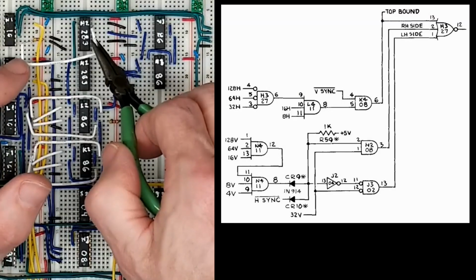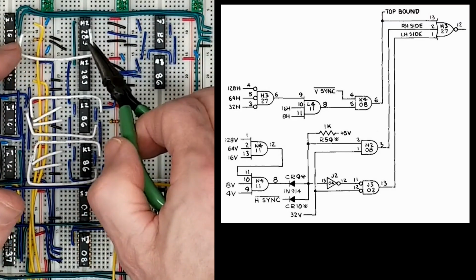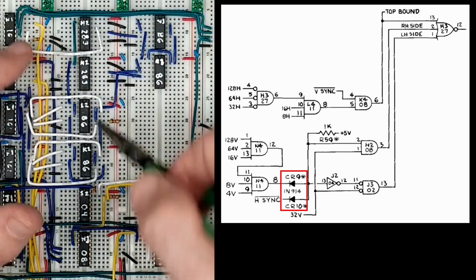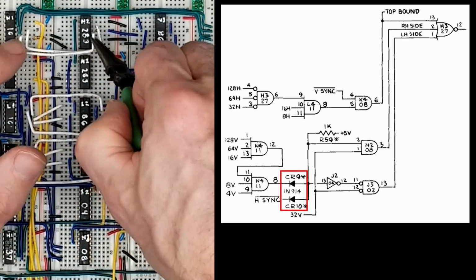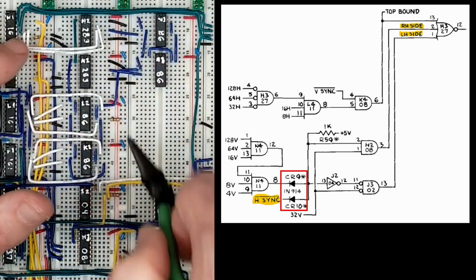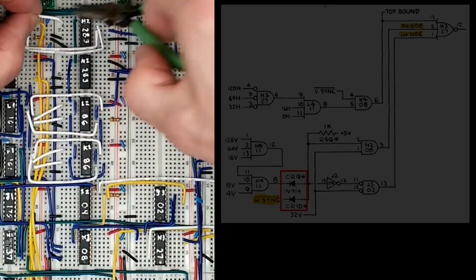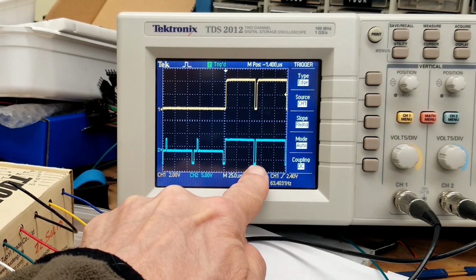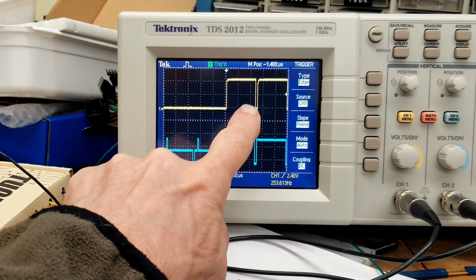In the corrected RevFX schematics, we see that these two diodes were added in an engineering change between board revs D and E to keep the left and right sides out of H-Sync. If we temporarily disable this, we can see that the left and right sides bleed into the H-Sync pulses in the composite video, something that evidently needed shoring up before ramping up production.